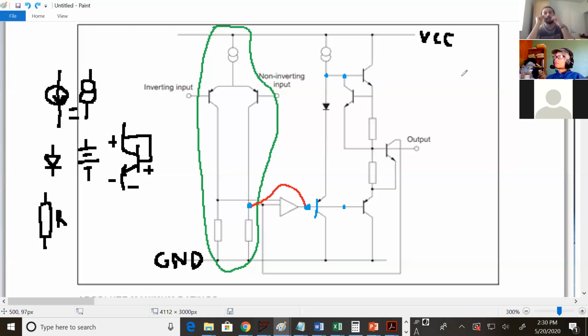And what are the characteristics of a common collector? High input resistance, low output resistance. Yeah. So now the output stage can pull current from the common collector, and the common collector won't pull current from your diff pair, so it'll protect the diff pair. It might just be there for the shift, but